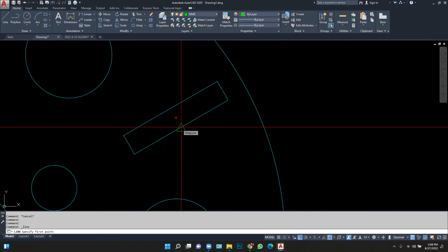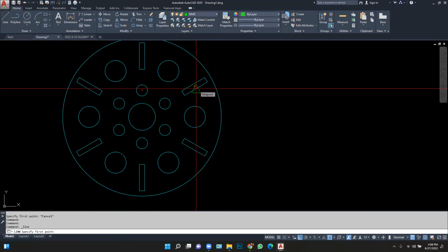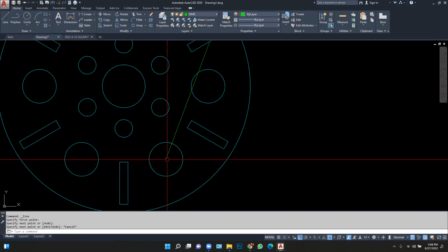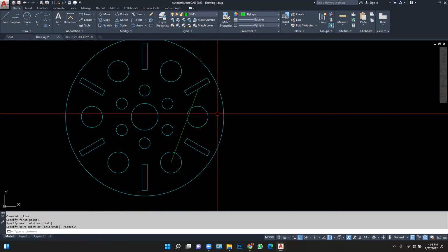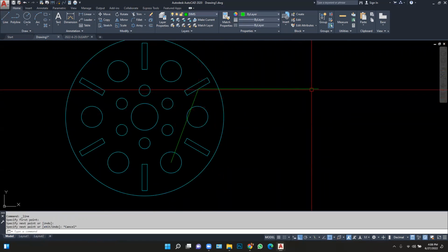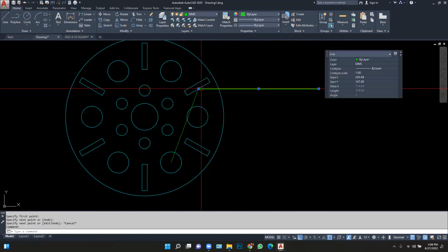This is the line. This is the midpoint of line A. So the midpoint of line A to the center of the 20 diameter B. So I want you to go from here to the center of B. That's where the center point is, if you were drawing this by hand with a compass, that's where you put the needle of the compass. So the center of B from A. The angle formed in the XY plane. So what that means is, if this is the 0, you come around halfway is 180 plus whatever the remainder is.